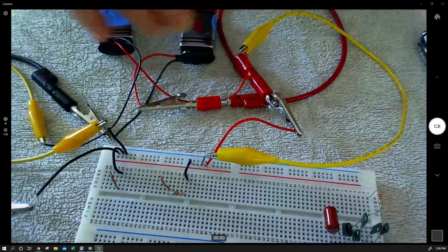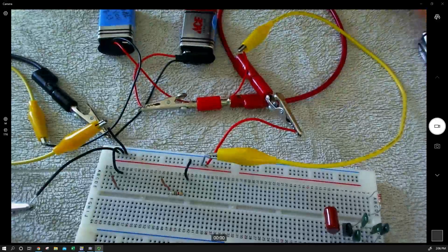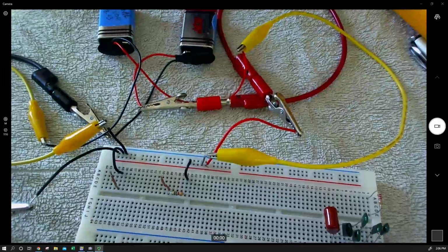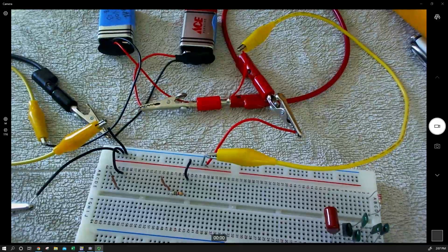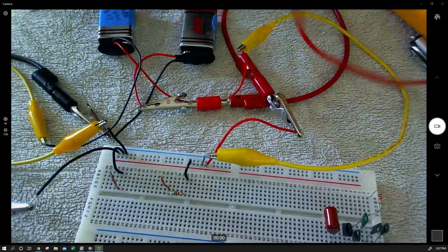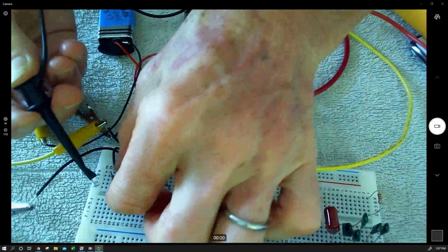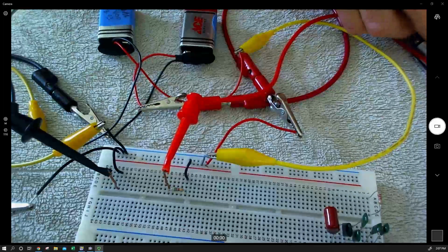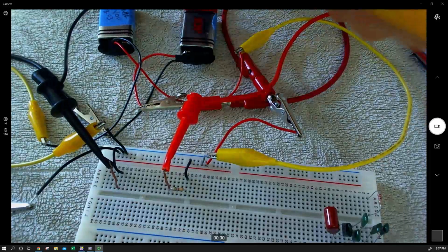So I'm going to take my meter again, and I'm going to measure DC current. So if you have a meter that defaults to AC, remember to push the toggle button to make sure you're measuring in DC. So I'm going to do the same thing. And if, as I suspect, I'm limited by the resistance of the load, I shouldn't really get substantially higher current with the double source.